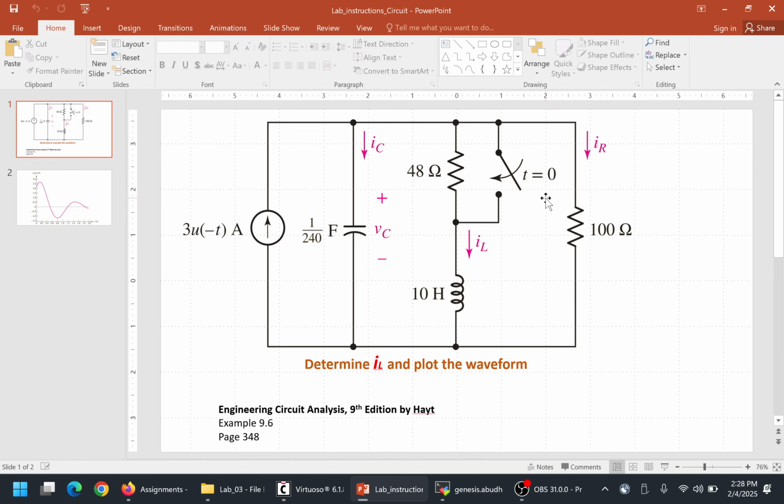This is just for the purpose of simulation, because starting at time equal to 0, we would be looking at the beginning of the transients. The transients are very short-lived, so I just want to give it some room, and I want to see the response at 1 second. So we'll just start the simulation at 1 second instead of 0. Nothing wrong with it, all right?